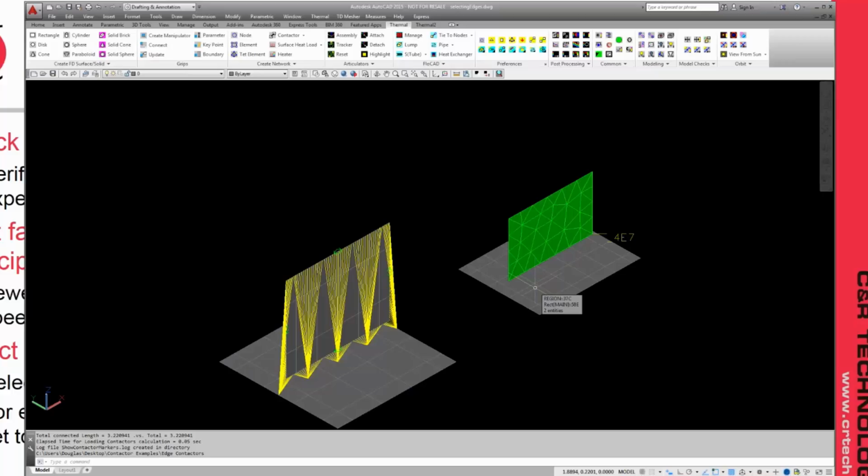This connects every edge up to that lower board, which is most likely not correct. I could go through and use the tolerance to limit just to the bottom edge, but then I'm doing all these tests around here. So that's inefficient use of my test points. So a much better way is to make sure that you're picking just the right faces that you want.